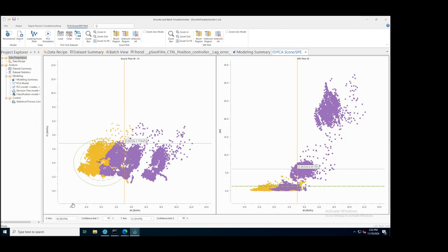On the left-hand side, the first very noticeable thing is that we have a separation into clusters along the x-axis, or this T0 axis. And then we also, in terms of our residual error, have quite a large degradation in terms of prediction error, which is exactly what we want. We want to see this because this gives us a framework to determine if the blade is degrading over time. So one simple way of interpreting this is you'll notice that we have these dashed green and solid green lines, which indicate to us where 95% and 99% confidence intervals are for our new blade data set. So if we take this and say that we know that 99% of our original data fitted below this threshold, anything above this is truly abnormal operation. And we could use this inside our deployment system to flag this.